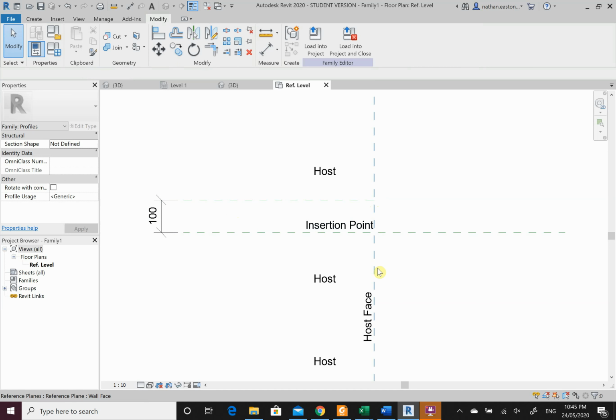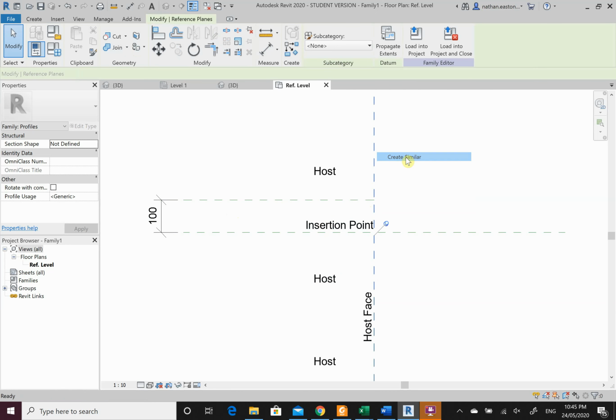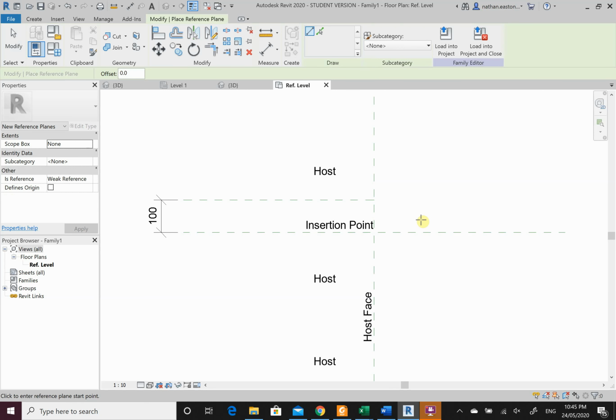Now what I have is my footing is 300mm wide. Every 100mm wider, I have to increase 1 bar top and bottom. So we typically try to keep them at 300mm wide. So if I go right click, create similar, I know on this side I have 150 coming out, which means I have 150 coming this way. So 150.